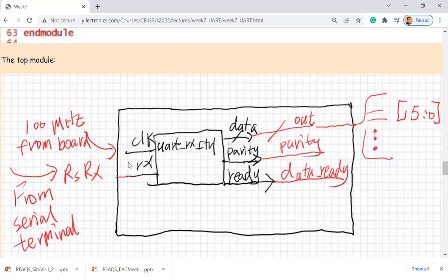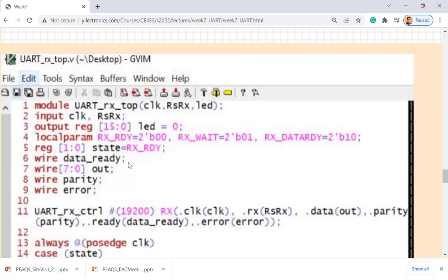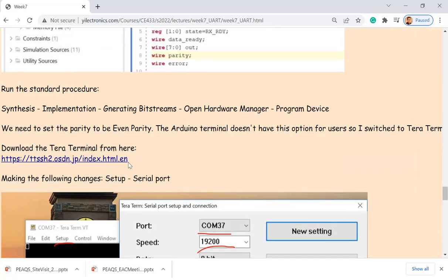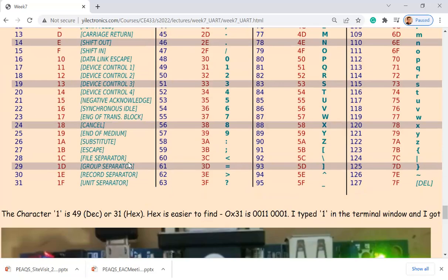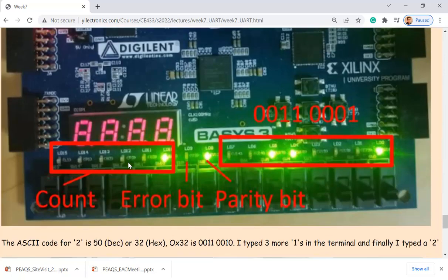So the FPGA is connected to the laptop using USB. Why is it RX TX? Why is it UART? There's a USB to UART converter on the board. It's the same as your Arduino. The little chip right behind that USB port is a USB to UART converter, so it's doing UART, and you should have that terminal and shoot a video.